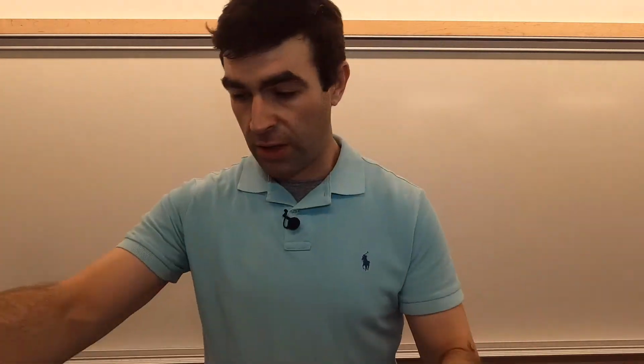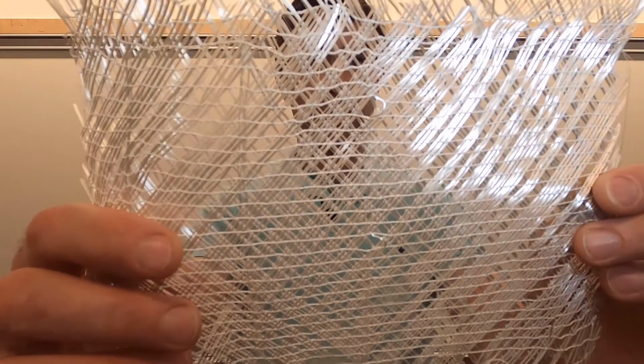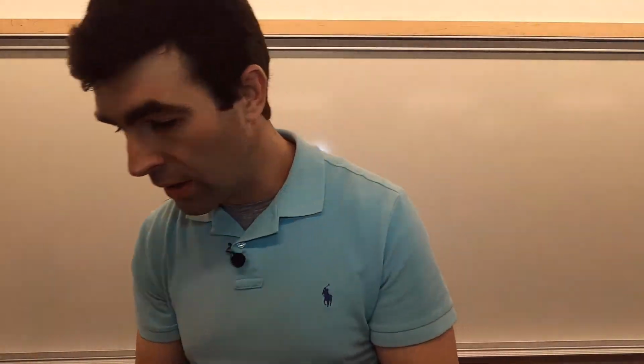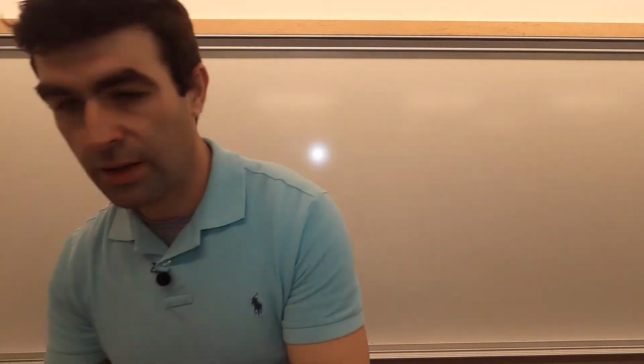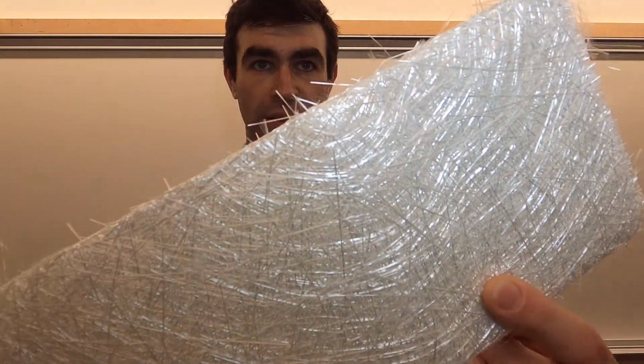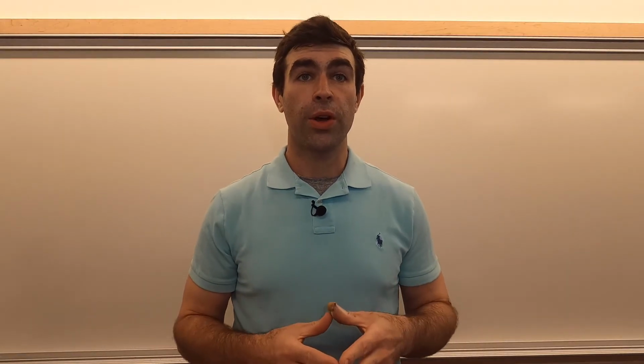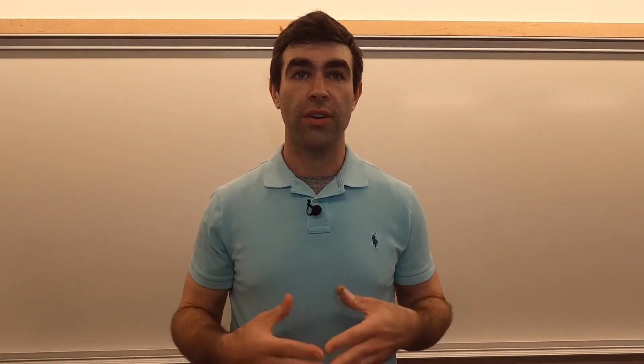It's going to come either with directional strands like this. This is a 90 degree, or something called biaxial cloth, which has 45 degrees, or it can come in random patterns, and this is what a chop gun will give you. The higher strength will come from the directional fibers.